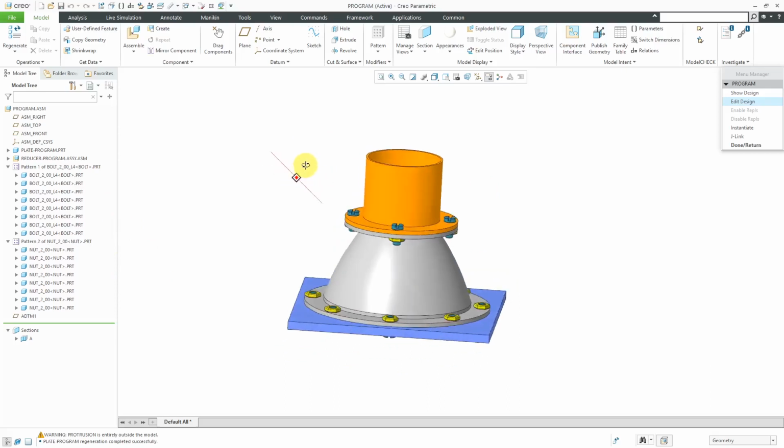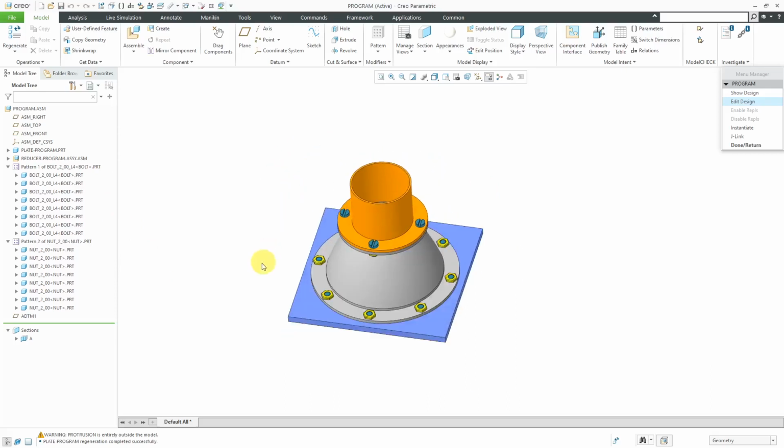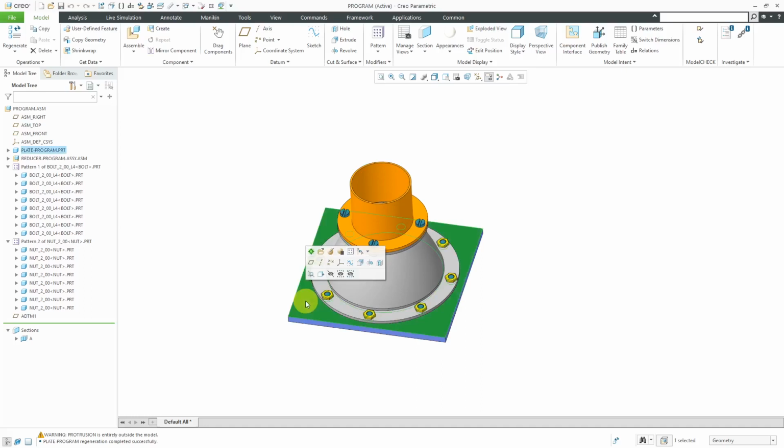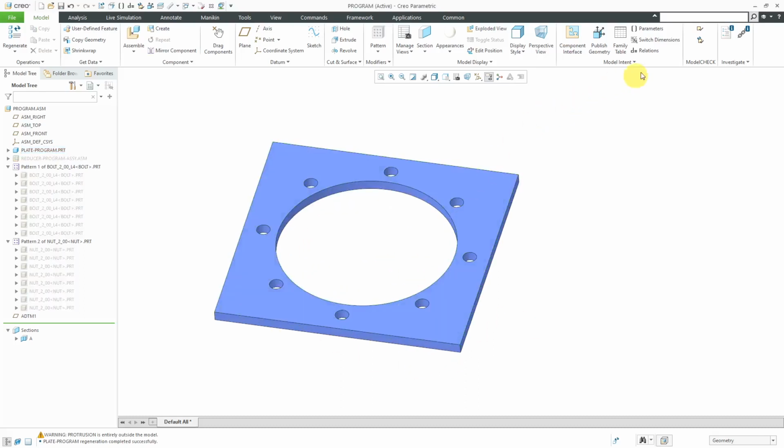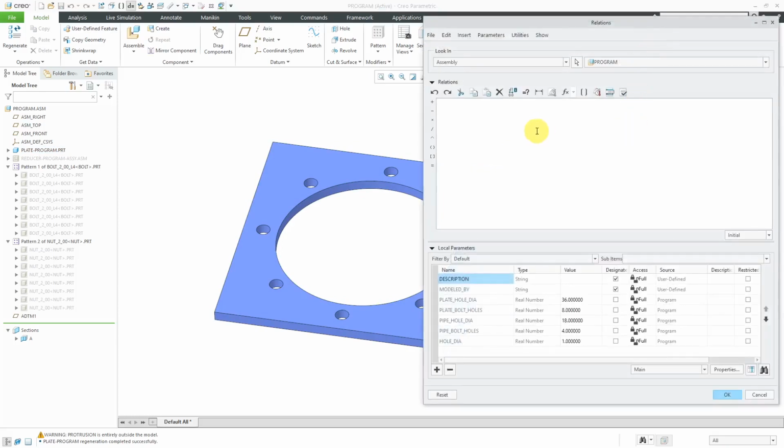And now let's say I wanted to have the different diameters of components driven by that relation. I'll show you how to do it manually using the standard relations dialog box. Let me select this component to begin with, and I will choose to isolate or show only this particular component. There you can see the different holes in here. I will go to the relations dialog box, and let's start off with a comment line, / and an asterisk. And I'm going to control the hole diameter in components by input variable.